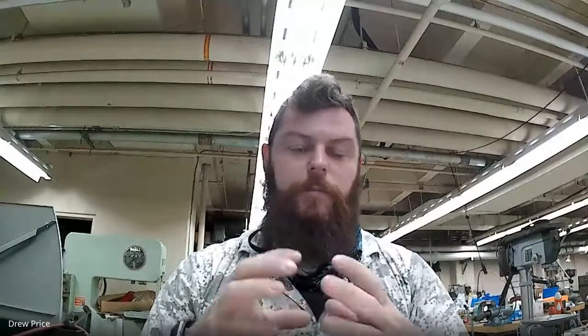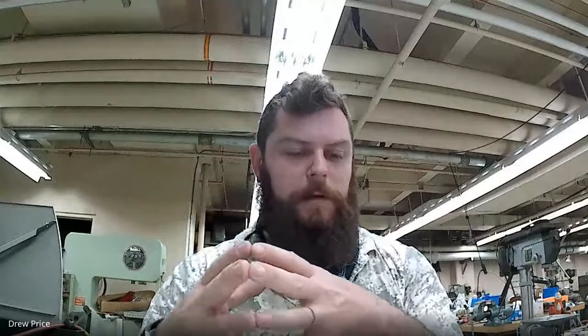Tolerances are important because they dictate a lot about how your designs will interact with individual parts of the design or other things in their environment, or manufacturing cost, and lots of other things. So tolerances at the very basic level determine how close duplicate parts are to being perfect copies of each other. And they dictate how parts either fit together or don't fit together. And they also dictate how much your parts cost, how much your design might cost to manufacture in small quantities or large quantities, or over the course of some period of time.